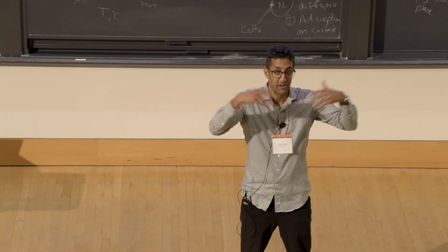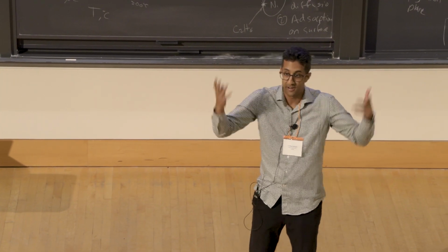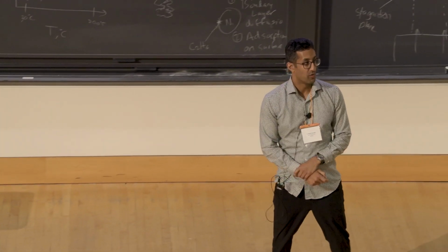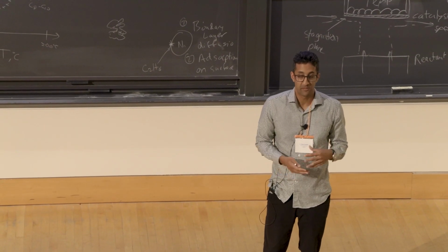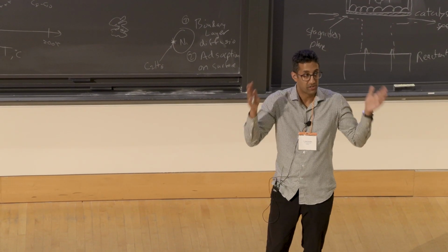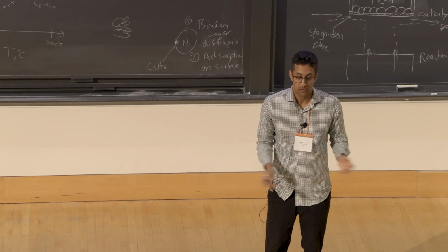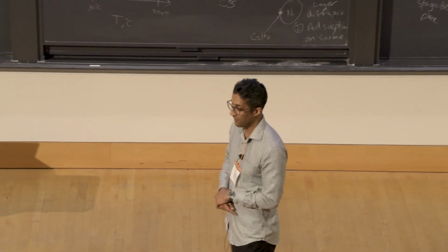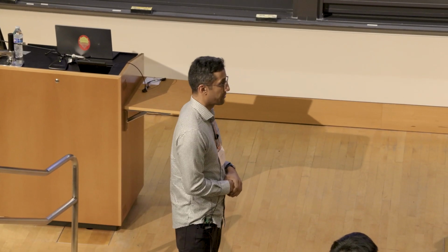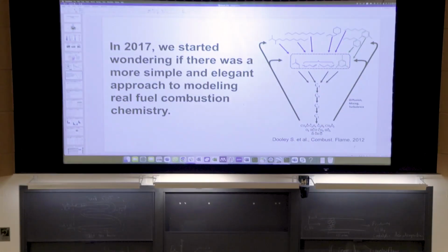You put them all together, now you have a huge model, which is very difficult to deal with in any practical combustion simulation, even for a CFD simulation. It's impossible to include the kinetics of all these things. So you do a lot of reduction, and in the end, you might defeat the purpose of what you tried to achieve in the first place. So in that sense, combustion communities start to think about how do we simplify this process.